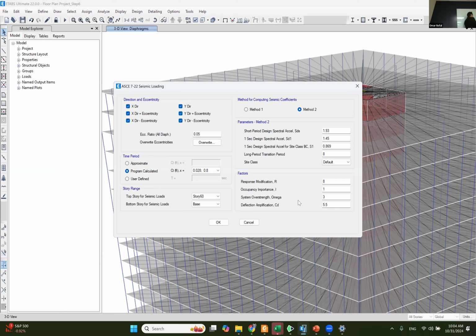We are gonna assume that the center of mass is shifted a little bit from the center of inertia. Okay. And this eccentricity, they say it's 5% of the length perpendicular to the load. If the load is hitting this way, it's 5% of this length. If the load is hitting from this way, it's 5% of the other length. So that's what the standards do.